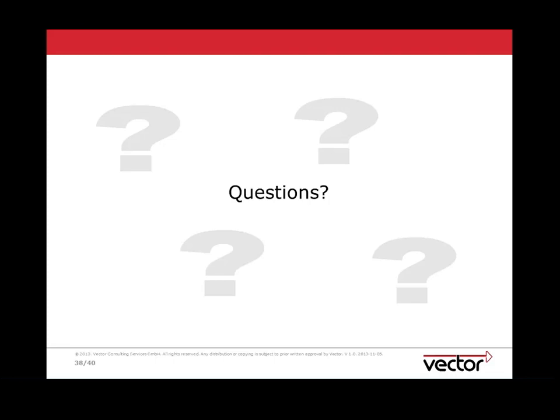I think I got a lot more questions, but they're hard to figure out. Let's take just one question. There was one question if, with the introduction of the ISO 26262, the FMEA will be eliminated, which is of course definitely not the case. The ISO requires you from ASIL A to perform an FMEA on hardware level for every system you develop.